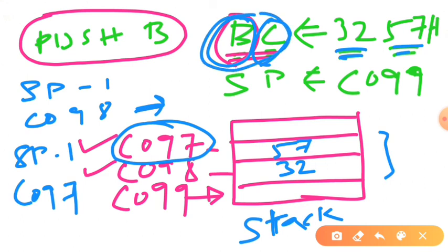We must know that the push and pop instructions are all 1 byte instructions. So if we want to write this instruction in memory, we need only a single byte, where we write the corresponding hex code of that particular instruction. It will be sufficient. Now let us understand one example of a pop instruction.